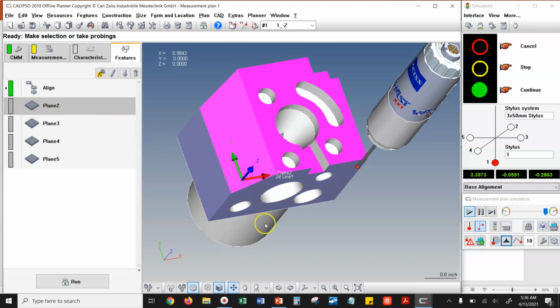Keep in mind, every regular rectangular tolerance has some degree of GD&T built into it. So if you're using a GD&T tolerance, that's going to be tighter than the existing rectangular dimensions that are already on the print. So a lot of times GD&T by definition is just a tighter tolerance than other tolerances. It makes sense to scan when you have tight tolerances.